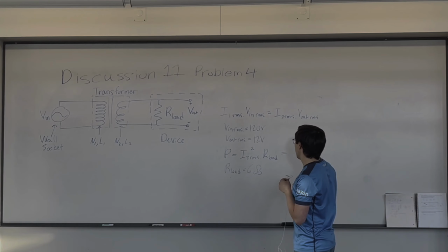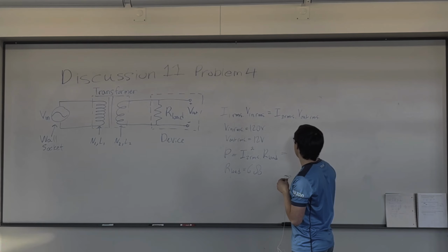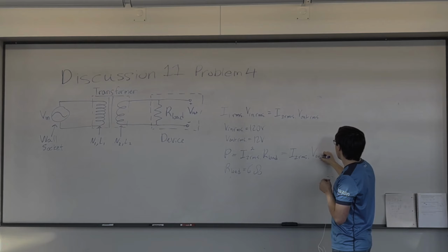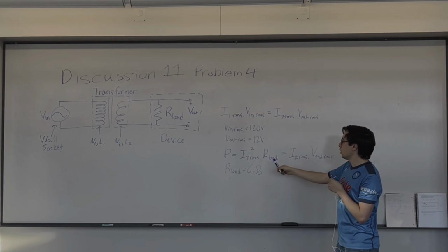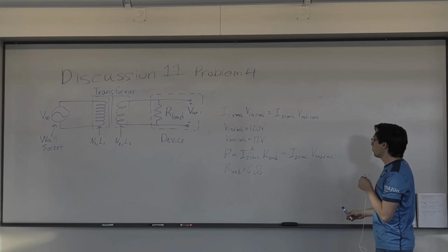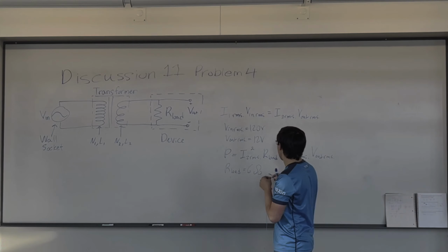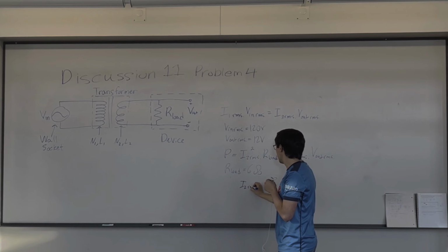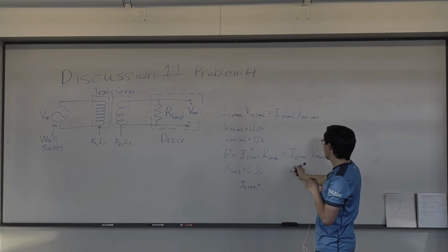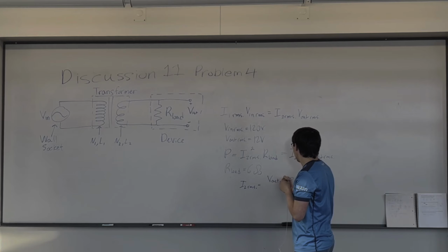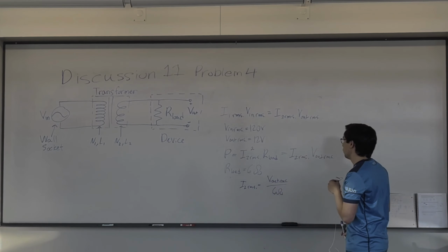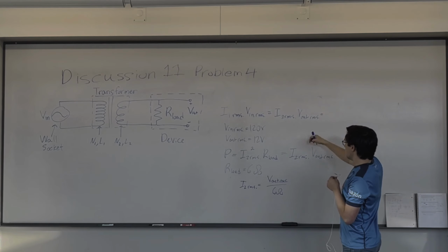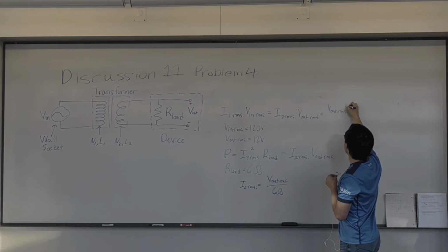We can also write this as I2 RMS times V out RMS. Right? This is just our IV formula, which is the same as I squared R for our resistor. And so by comparing these two, that I2 RMS equals, well, let's divide through here a little bit. We get V out RMS over 6 ohms. And using this piece of information, we can substitute. We can say that this is V out RMS squared over 6.